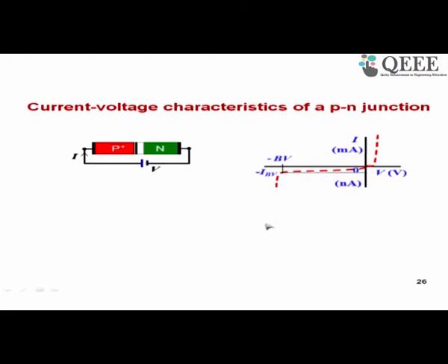As engineers, we should pay particular attention to the magnitudes of quantities, orders of magnitudes of quantities that are used here, right? So the voltage axis is in volts and the current axis is in milliamperes here, because we are discussing a small signal device. Further, another important thing you find here is that the positive current axis, which gives forward bias currents, is in milliampere scale, whereas the negative vertical axis, which gives the reverse current, is in nanoampere scale. So the two scales are not the same.